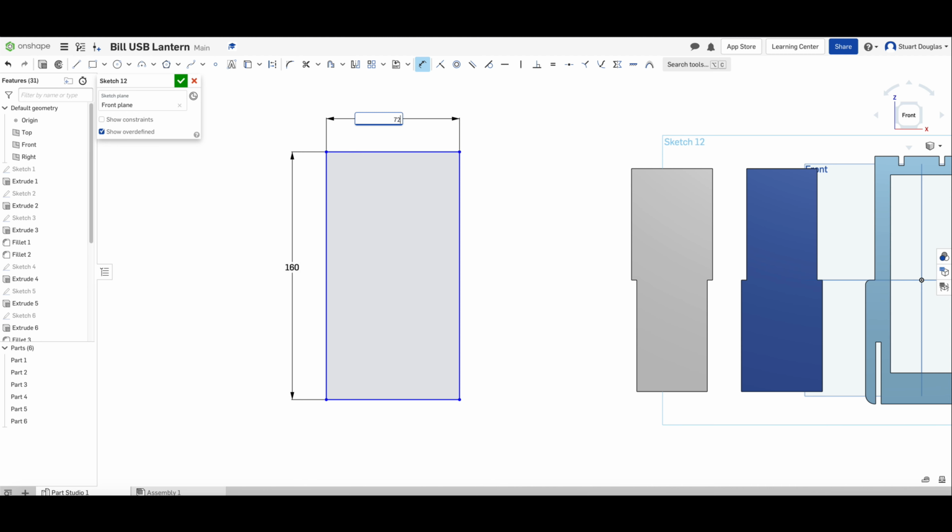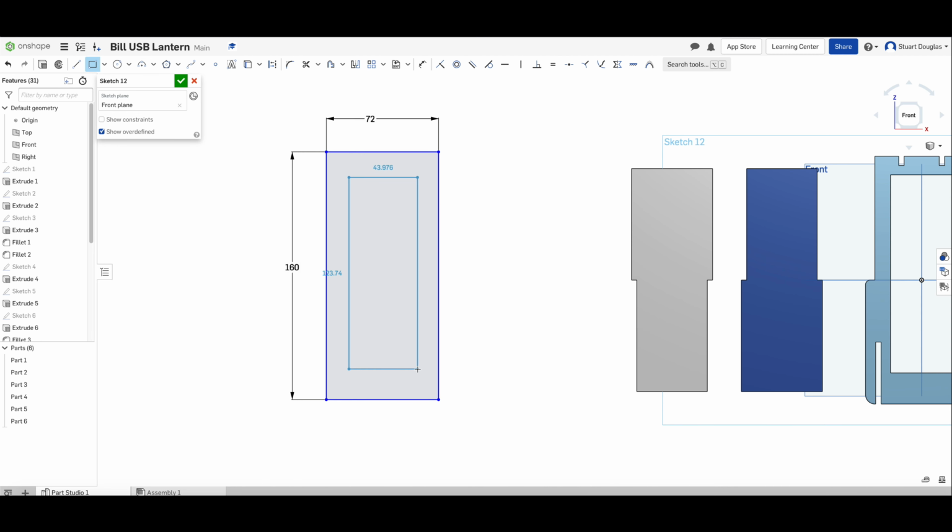by 72. Okay. Now what I need to do is model the details. So this one is perhaps slightly easier than the other wooden panel design. So we'll start off by adding another rectangle on the inside of my work. Okay, this has a width of 40 millimeters and has a total height of 128. It's the same window as in the other design over here.